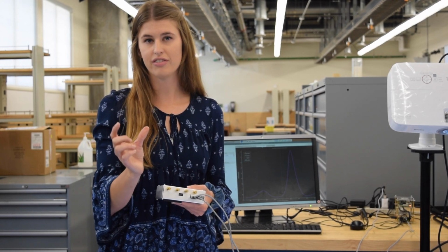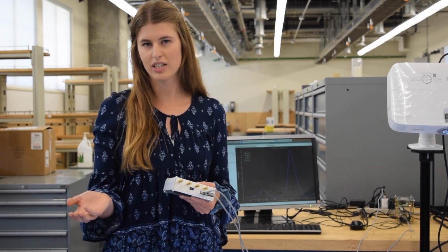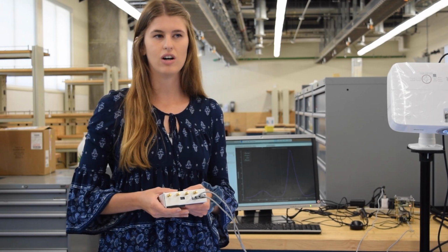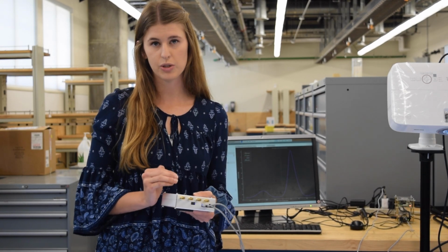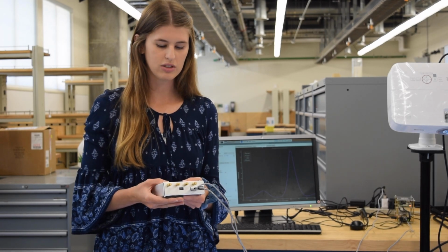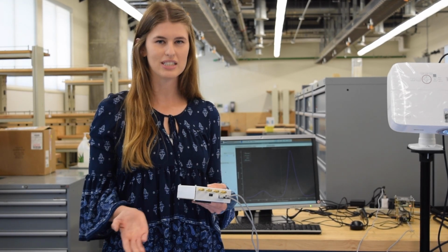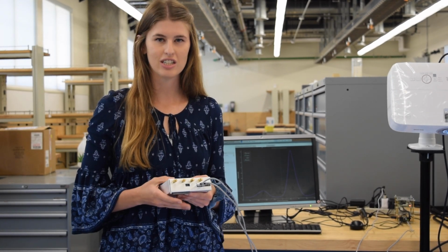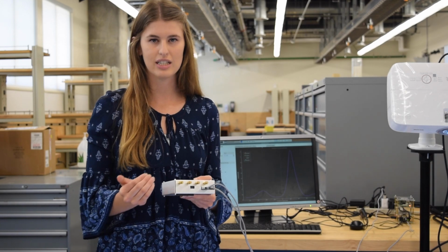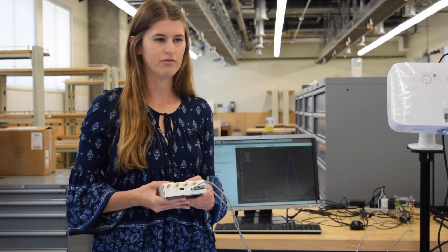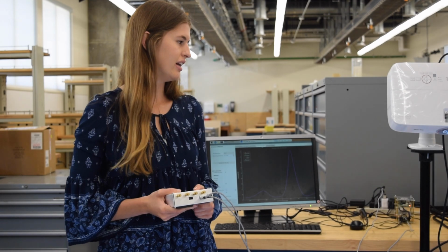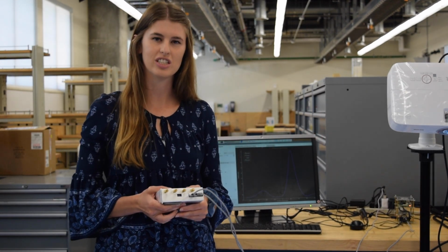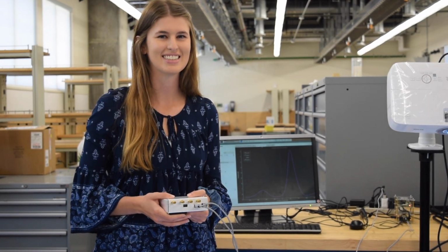We can change the FIR filter size, the decimation factor, the gain of the RTLs, and then also we can choose which DOA algorithm we want to use. And we're using the MUSIC algorithm as it's one of the best algorithms. And so this little SDR does it all. It takes in the signal, processes it, amplifies it, filters it, decimates it, and then it outputs an angle, which is then used in our visualization system that you'll see next.